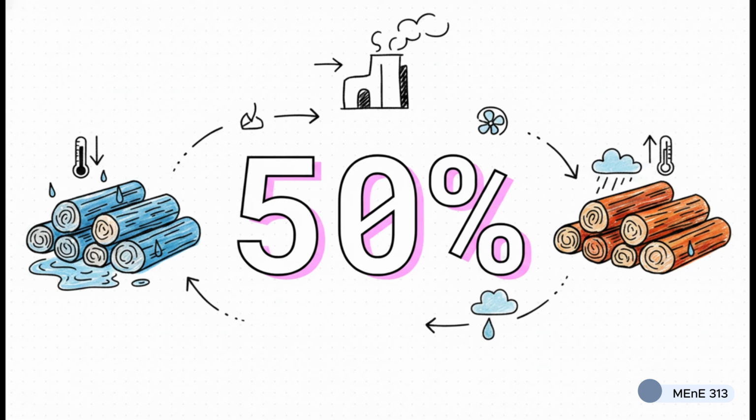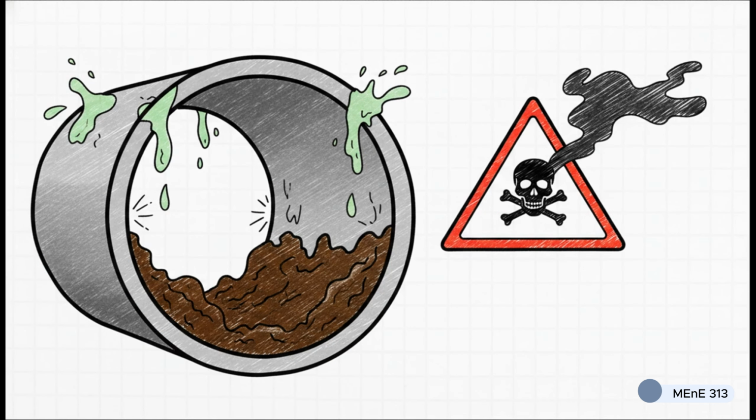Two pieces of the exact same material will perform radically differently if one was left out in the rain. Moisture content can actually dominate fuel quality way more than the underlying waste category itself. Beyond moisture, you've got chemical properties like ash content, chlorine, and sulfur. These are absolute deal breakers. They tell us if a waste is going to destroy our reactors.